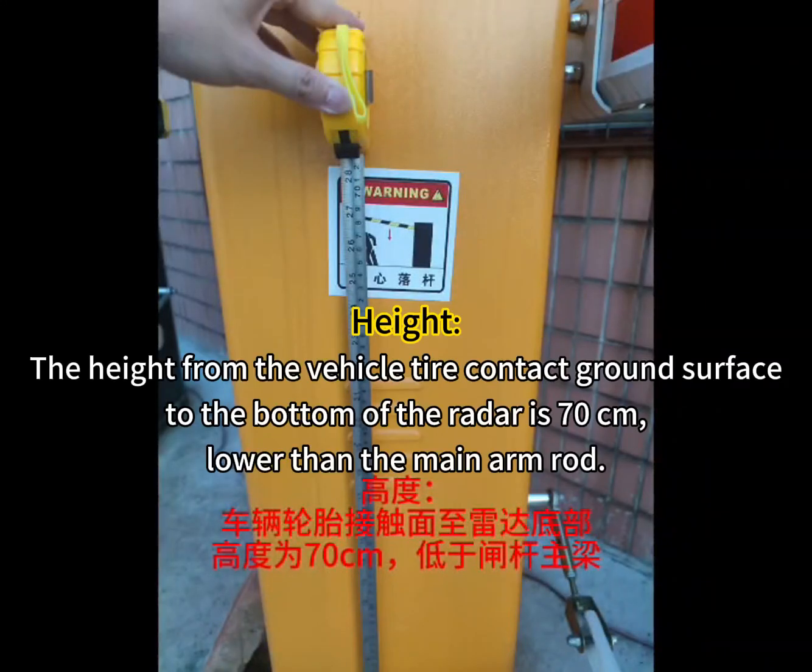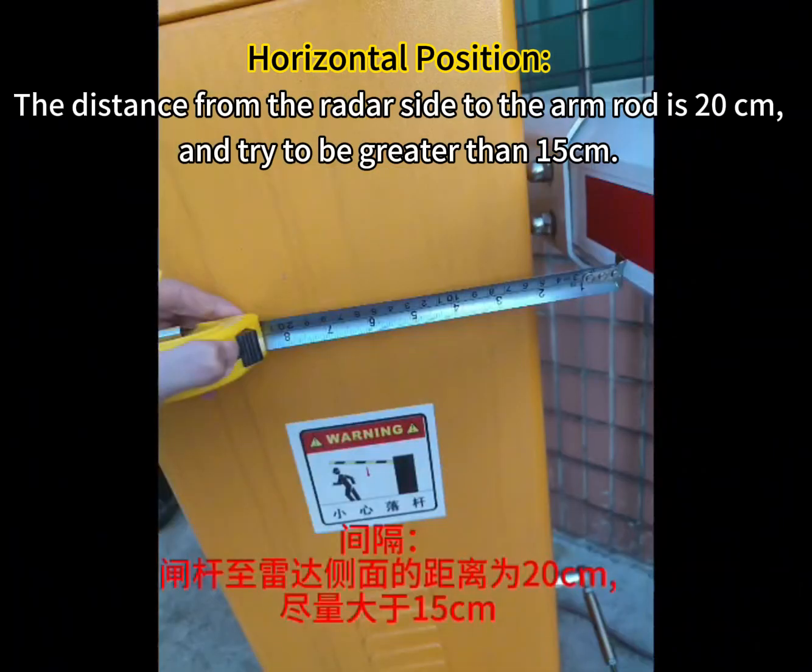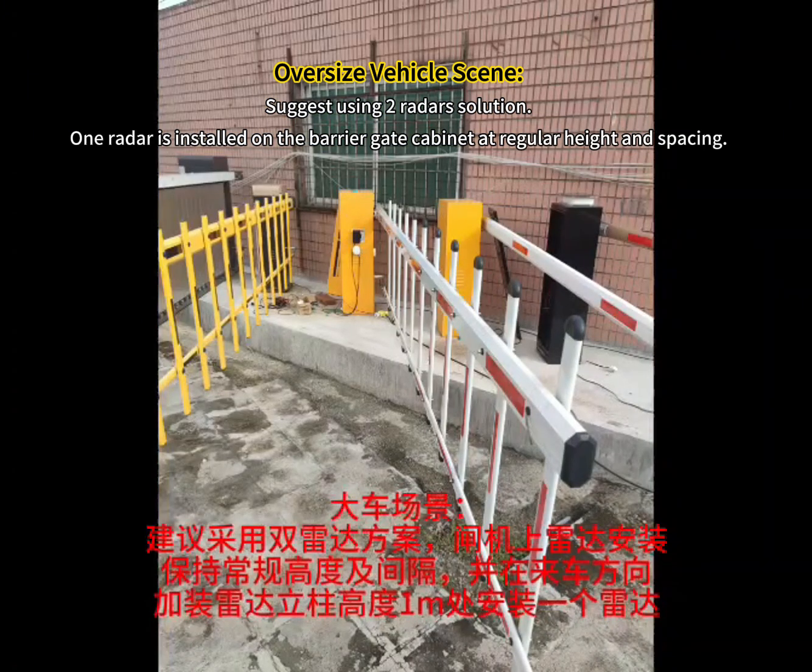Height. The height from the vehicle tire contact ground surface to the bottom of the radar is 70 cm, lower than the main arm rod. Horizontal position. The distance from the radar side to the arm rod is 20 cm, and try to be greater than 15 cm.